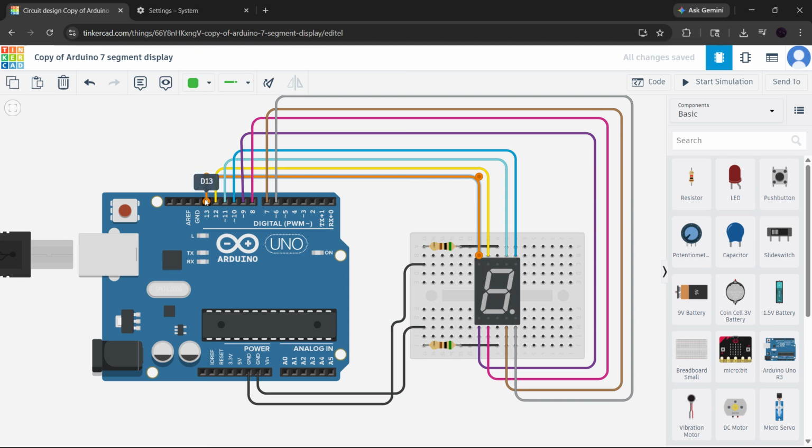To test this, click and drag each component gently. If the component moves but the wires do not move with it, that's a sign the connection was not properly made. Reseat the part and make sure every pin is fully aligned with the breadboard holes.